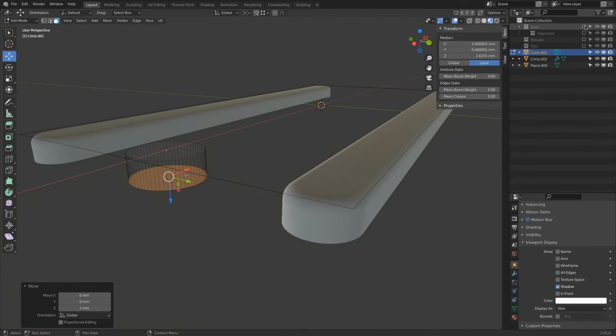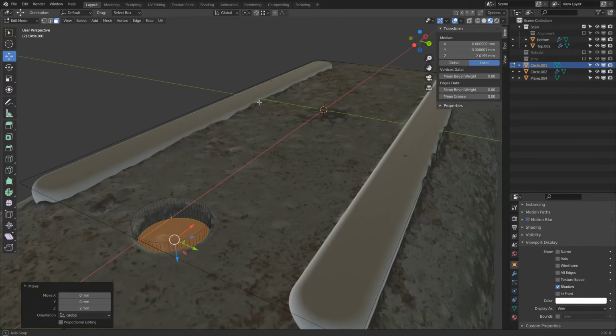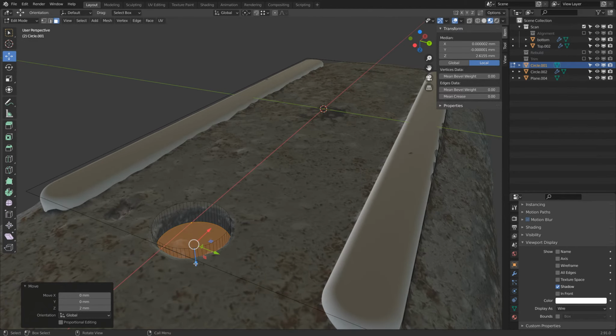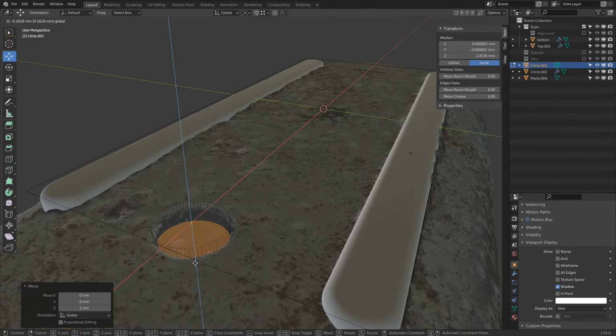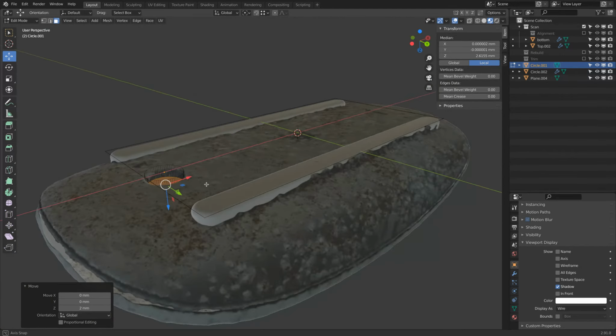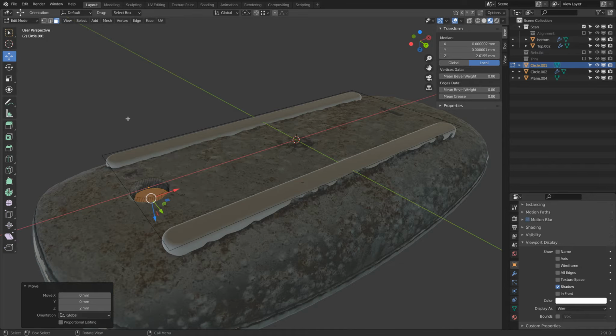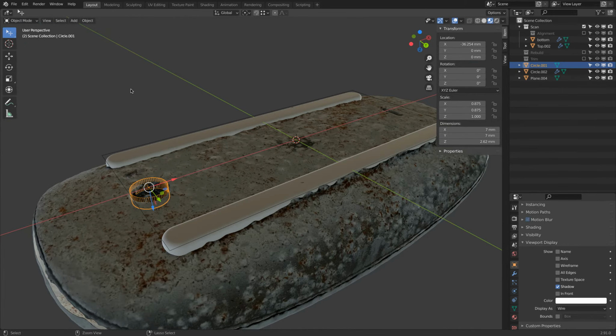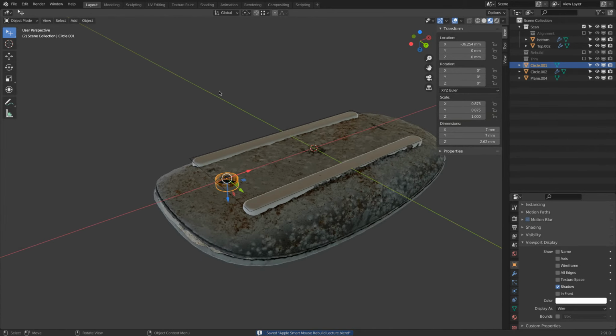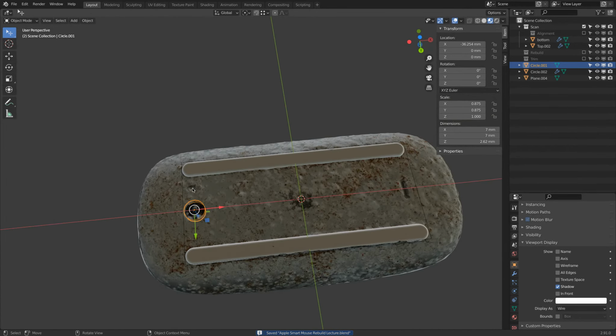Okay. And also here again, we can turn this as a wireframe. Main reason why I do this is now I can see actually how far this is going down. Oh, there's actually now the optics. So something like 2 millimeters for what we try to do here is fine. Very good. Back to object mode. Control S a few times to save. Now the last two things to model is the slider and the slot.